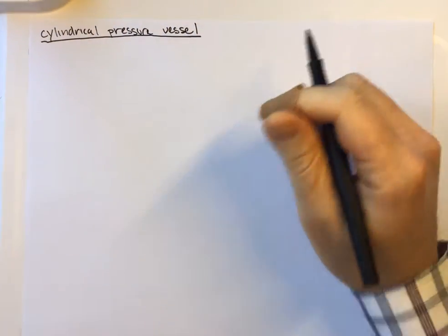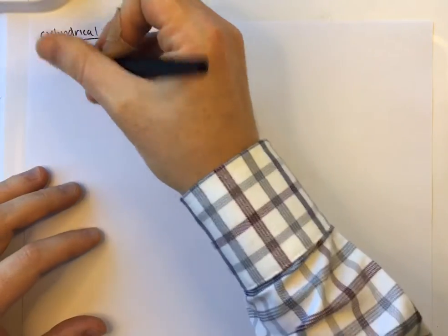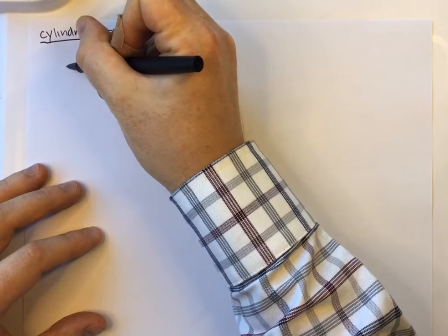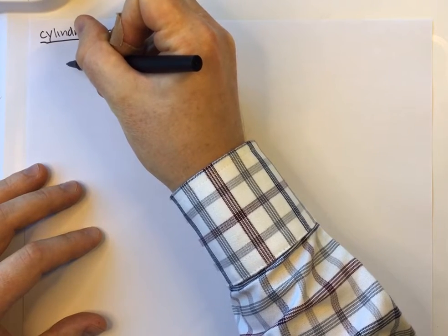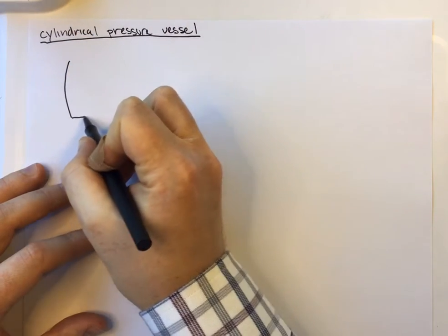Well, it turns out that if you have a cylinder or a sphere and you fill it with some pressurized fluid or gas, if the wall thickness of your pressure vessel is thin enough, you end up with a pretty much 2D stress state. You end up with that state of plane stress. And our requirement has some geometric requirements. We'll get into those. But it's nice to stay in 2D here to think about some of these transformations. So I'm going to draw a picture here.